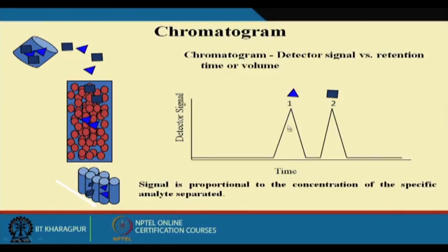So when you inject the standard, you find out what the retention time is and which component it stands for. With respect to the standard, you have to find out what each one is. First you have to identify what the different components present are. Then you have to inject the desired amount, because this chromatograph is used for a dual purpose: for qualitative analysis and quantitative analysis.